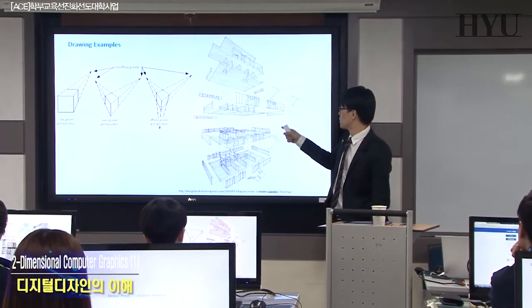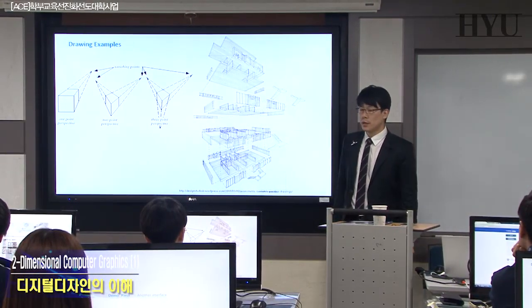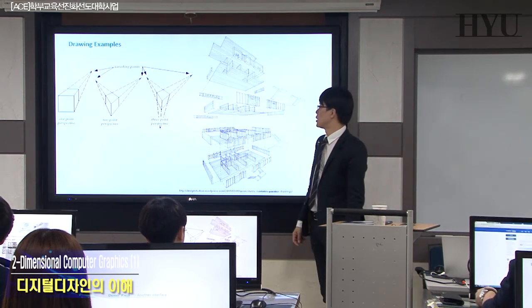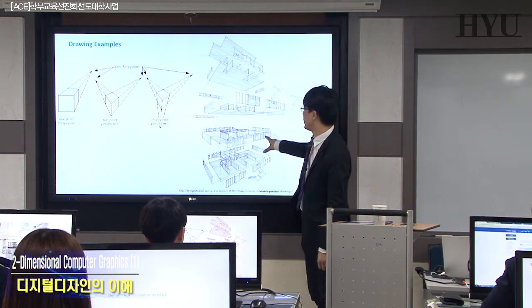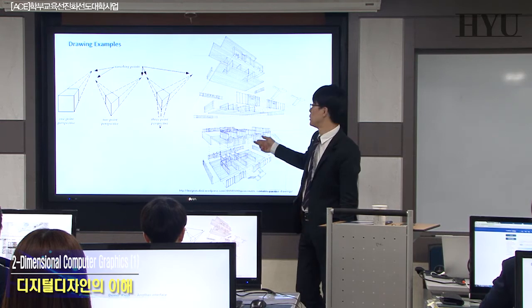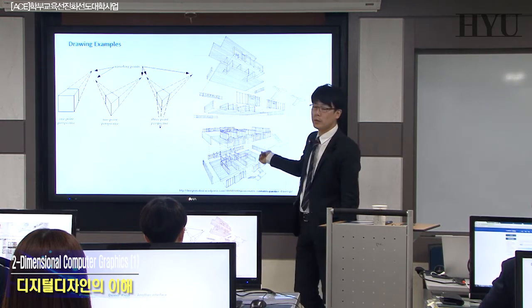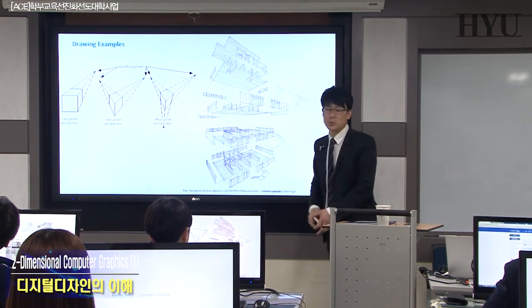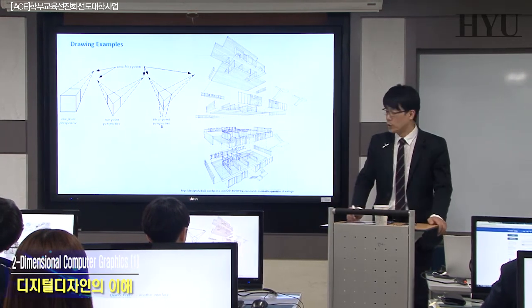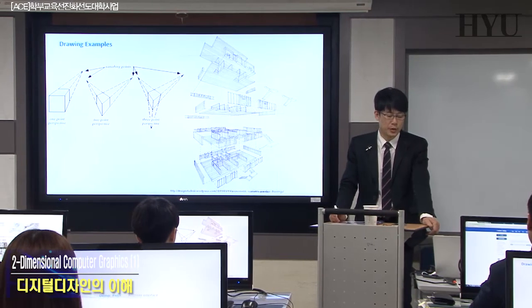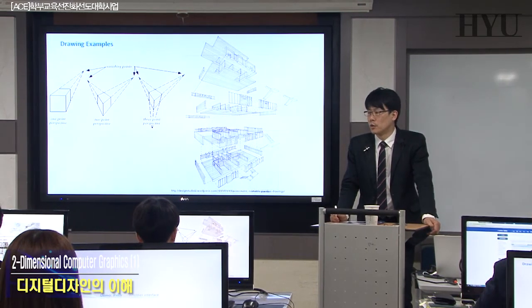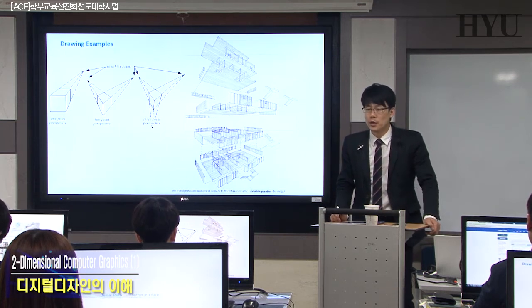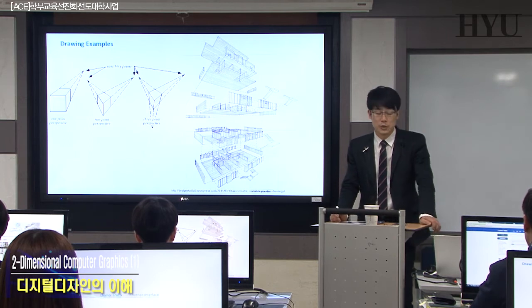And this one is exploded 3D perspective. Exploded building, very effective in drawing, but actually it's done by hand drawing. Anyway, this one also 2-point perspective, not 3-point perspective, okay? In architectural drawing, we usually use 2-point perspective because it's very professionally looking and effective, visually effective.